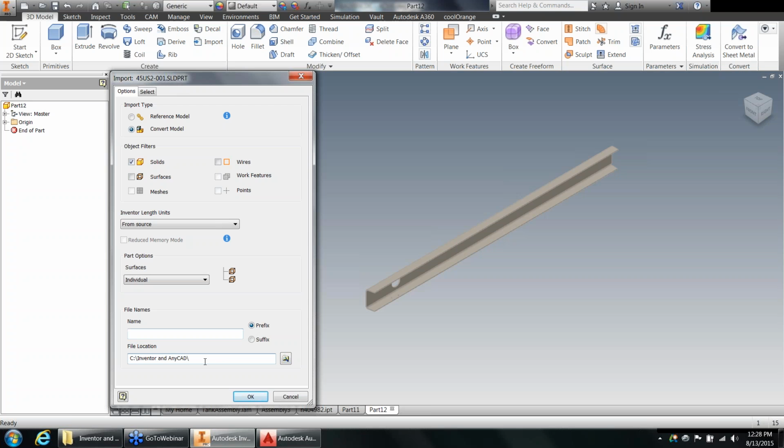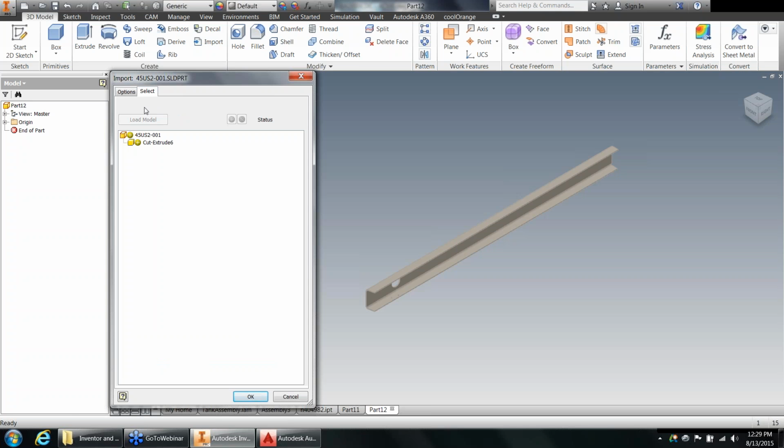So it's always a good idea to make sure that you're saving these files into an imported components directory or into a directory named the design files, because it does give you some functionality change in here that you've got to pay attention to. This is different from years past where it would just utilize the files. This will actually overwrite them, which can be kind of problematic depending on what files you already have in that location.